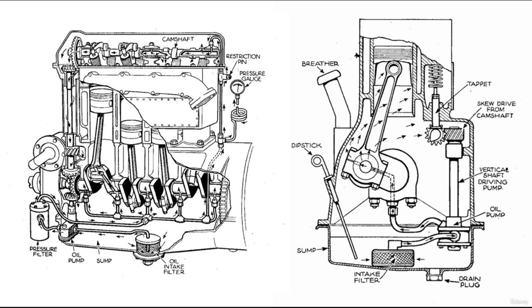An oil pump doesn't create oil pressure, it merely moves oil from one place to another. Oil pumps are positive displacement pumps. That is, the amount of oil that leaves the pump is the same amount that enters it. So output volume is proportional to pump speed. As engine RPM increases, pump output also increases.